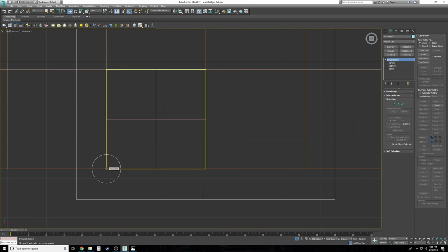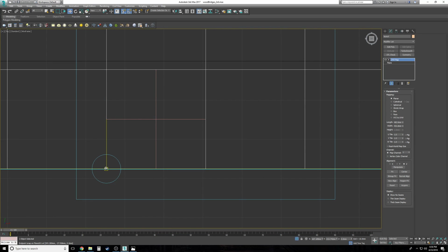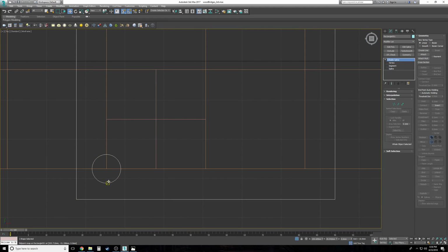You can set your point when you turn on your snap. You see how it's snapping all the way to the edge? You can make it in the center, and it's only snapping right there because I've got an object there, and it piggybacks off this object. And I can do that, but it's going to just grab the wrong piece. It's difficult to snap from a center point.